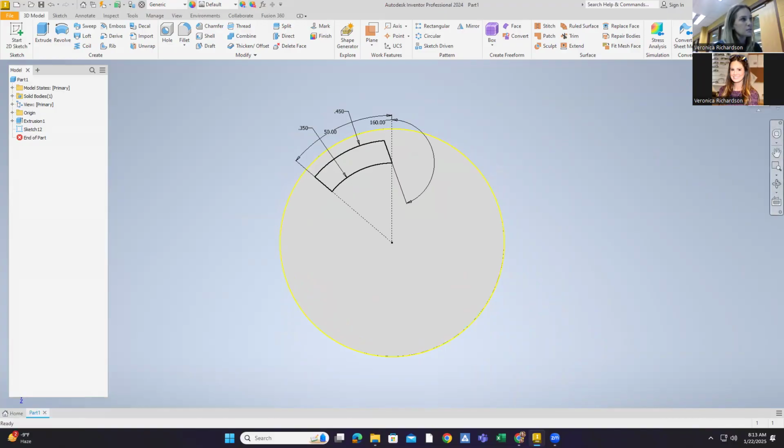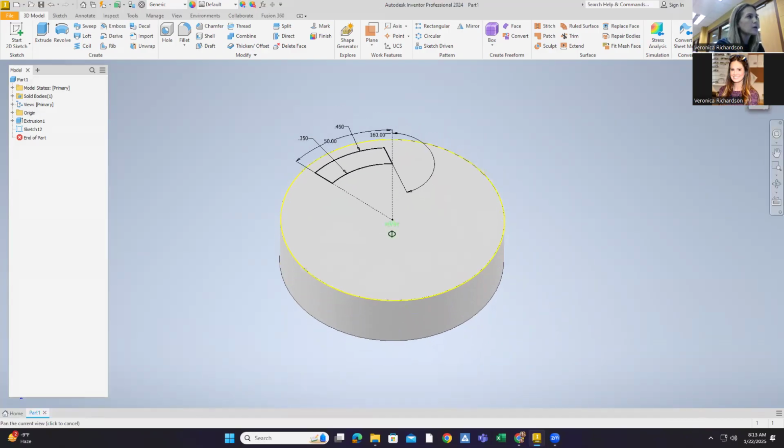So you're going to go up to the direction cube, which is up here in the top right-hand corner of your screen. You're going to click and hold right in the center of it, and you're going to push your mouse forward to rotate that back. Now that we're able to see the top and the side, these next couple steps are going to be much easier.